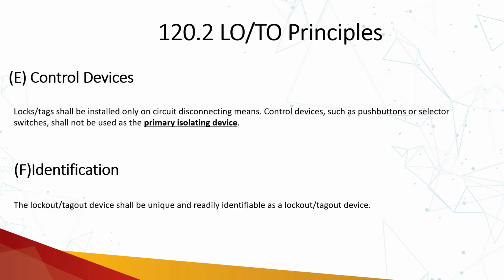I should not use that lock on the substation door for unauthorized access. If I'm putting that blue lock on the substation, that should reflect that this complete substation is under lockout and tagout, or that lockout and tagout have been performed on this particular substation.